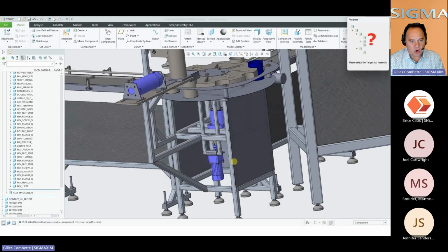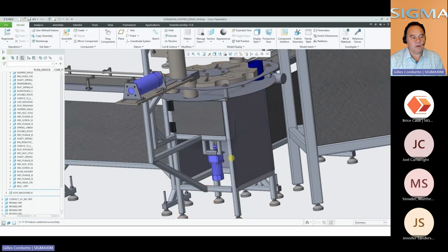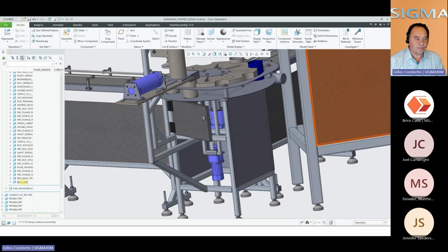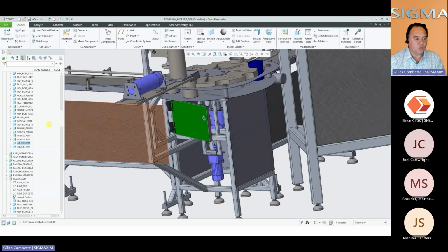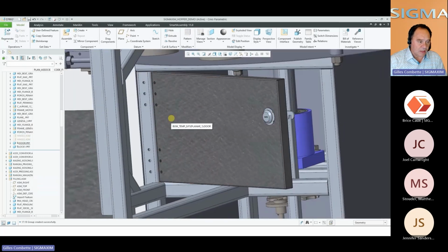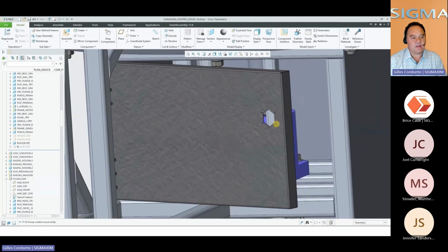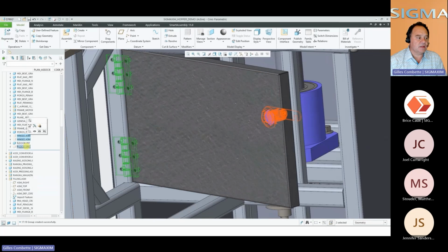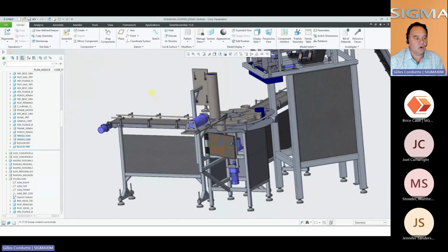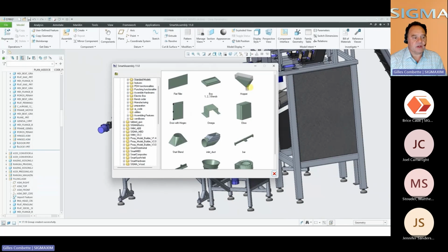We could make compositions of those basic elements, like the box, like the flat, etc. We illustrate this with the door that we're about to design here. What is a door? A door is a box that is held by hinges, and that includes a key lock. So the system is reusing in the background the automation for the box, placing the box, 1, 2, 3 bands, depending on what the setup was, placing the items that are necessary to define the so-called door. The items are generated with the hinges, and some of those items are placed there. And you see that every time we add standard components like hinges, like key locks, like all those kinds of things, the necessary cutout will be generated.